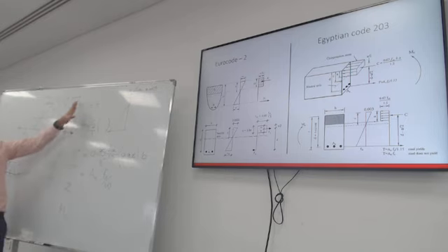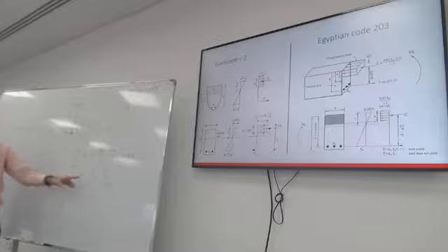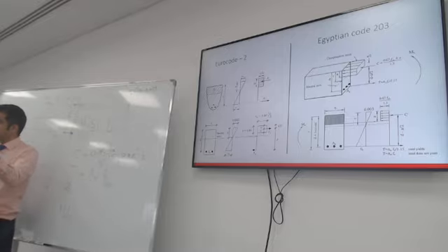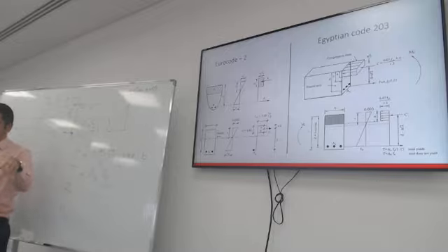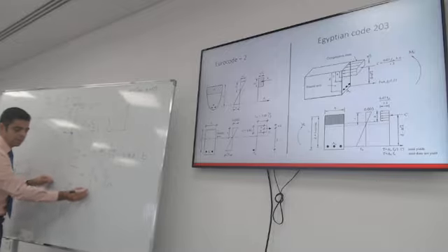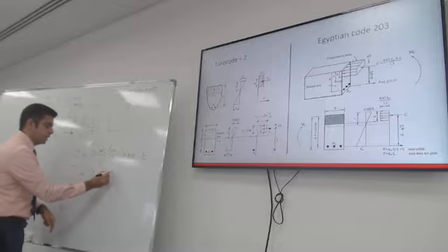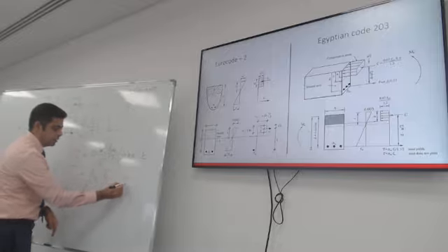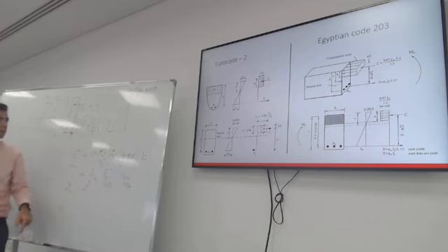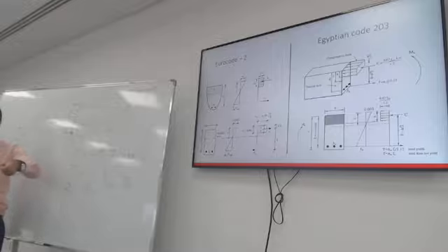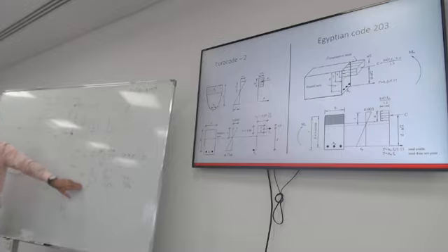We already said that for the section to be in equilibrium, tension needs to equal compression. So let's say I assume the area of steel is like 2 bars with a diameter of 20 millimeters or something. I can start with some assumption here. I know the F yield for steel. I will order bars with a certain characteristic yield, so let's assume it's like 500 MPa. And just by knowing the area of steel bars, we can know the tension at yield.